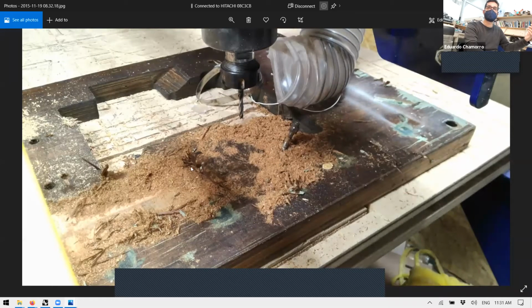So they were trying to cut the wood. This is a hard wood. It doesn't look like magnolia. I don't know what kind of wood this is, but the mill touched the screw, took it out, and broke everything. So it was a mess, super fast. Here the MDev students always try to use refurbished pieces of wood or pallets. Be really careful when you use a recycled piece of wood. There might be hidden nails somewhere, and you're going to break the mill.